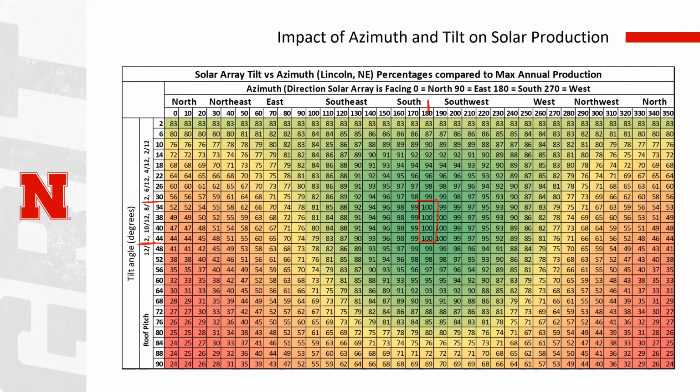Now, let's just say I have a roof and I want to put the solar on my roof, and it's a 4/12 pitch roof, which is really common. Really, you do not want to change the pitch angle of the solar because it's going to cost, and it's going to look ugly. And what's going to happen? I'm going to lose about 5%. There's my 4/12 pitch roof. So I think really the idea is just understand what you're losing and calculate your system based on that versus on the maximum, and understand that.